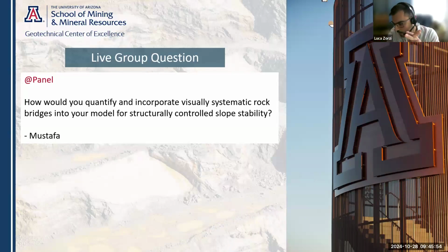Yeah, one approach that we use, once you define the damage zone of a fault system, we use a DFN approach, and you can actually do stochastically the representation of variability of the distribution on that one. One thing that I want to highlight, though, is that rock bridges is very much a stress term. What you consider to be a rock bridge, because you see two joints, discontinuities or faults that overlap and not connect, like with a hard linkage, doesn't mean that it's going to break, or it could mean that it's breaking anyway, because it's very much a stress related problem with rock bridges.